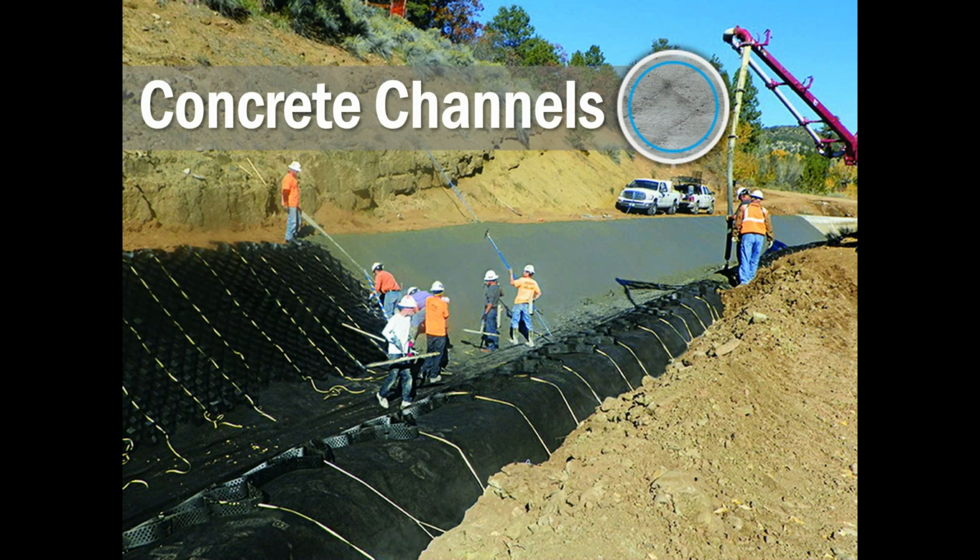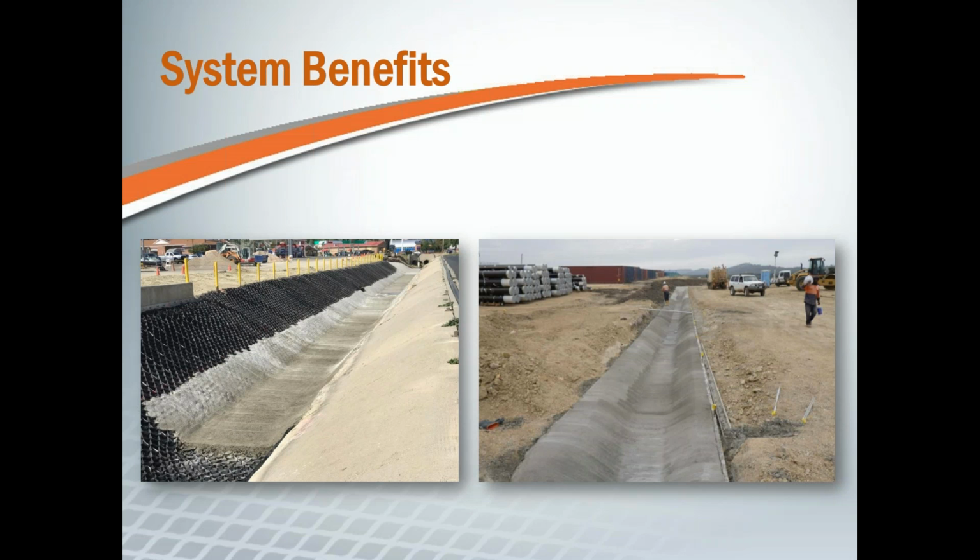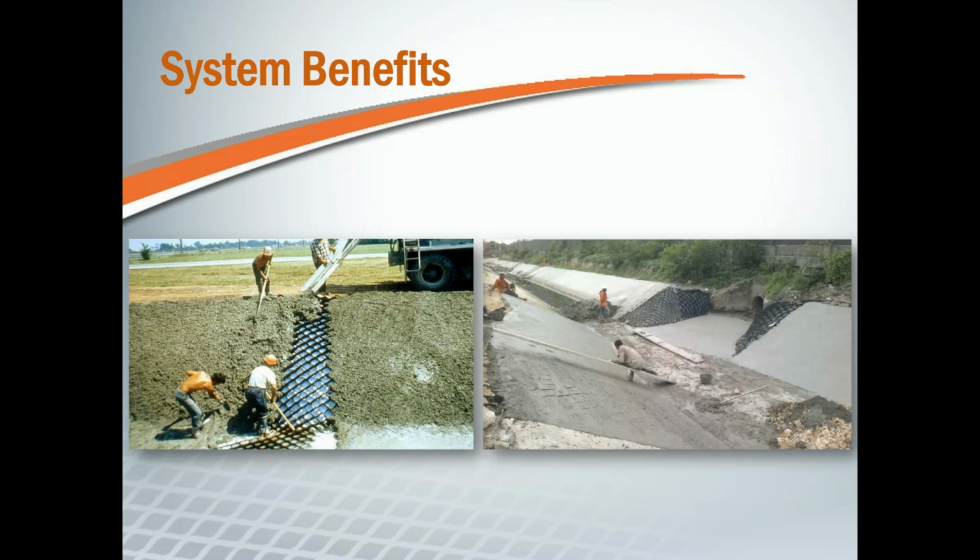So our second type of infill is concrete-filled channels, which are among the most beneficial GEOWEB channel applications. The GEOWEB allows for curves, dips, and other features of the landscape to be incorporated into the channel if desired. This allows for a more natural-looking channel and limits the amount of prep work required before construction can start. Because the GEOWEB panels act as the formwork for the concrete, they can also act as internal reinforcement. This means no additional reinforcement is necessary, no laying rebar or using fiber reinforcements.